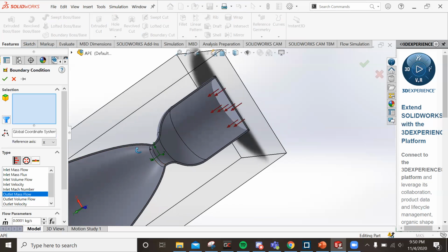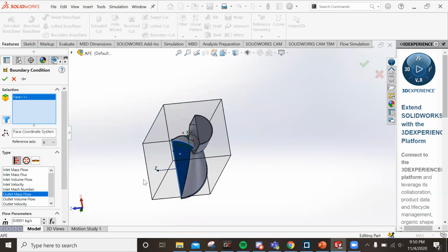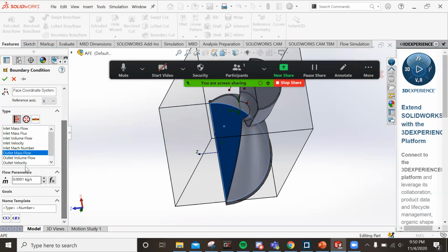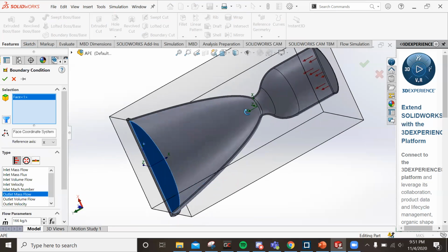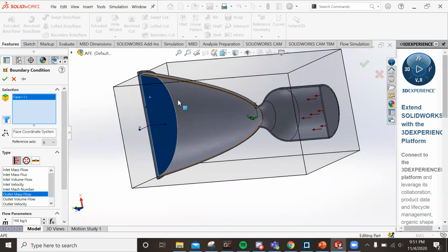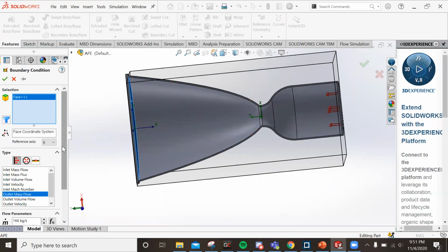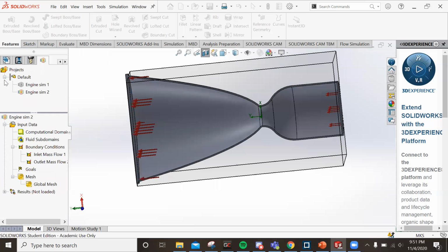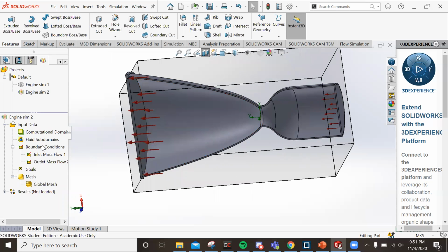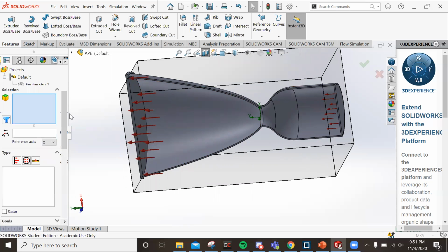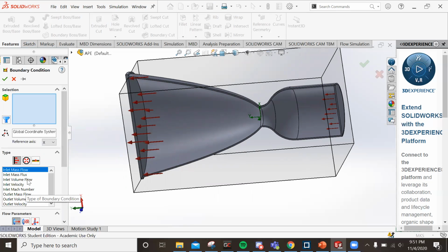We're going to define the outlet mass flow at the end of the nozzle. This one we just have to put in mass flow. There's no thermodynamic properties because this is an outlet mass flow rate and it's going to calculate what the thermodynamic properties are at this point based on the nozzle and everything. So go ahead and check that. Right click, insert. Third boundary condition is going to be a pressure opening.